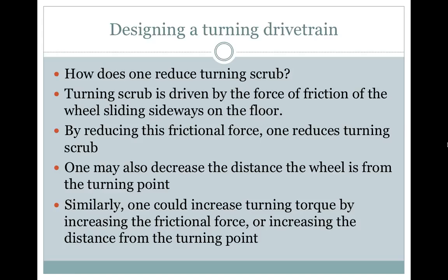Turning scrub is driven by the force of friction of the wheel sliding sideways on the floor. By reducing this frictional force, one reduces turning scrub. One may also decrease the distance the wheel is from the turning point. Similarly, one could increase turning torque by increasing the frictional force or increasing the distance from the turning point.